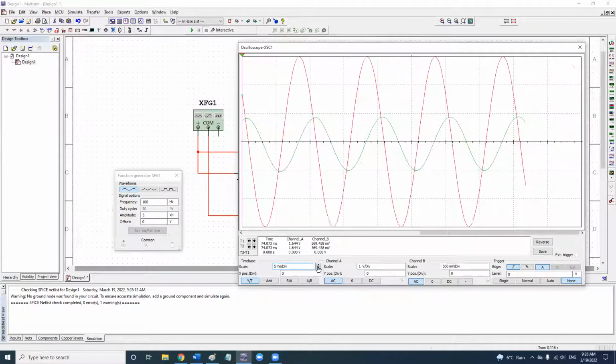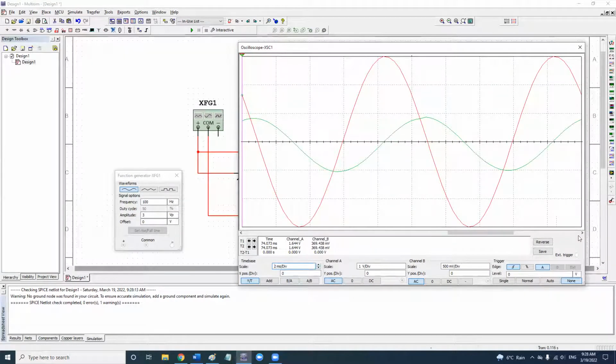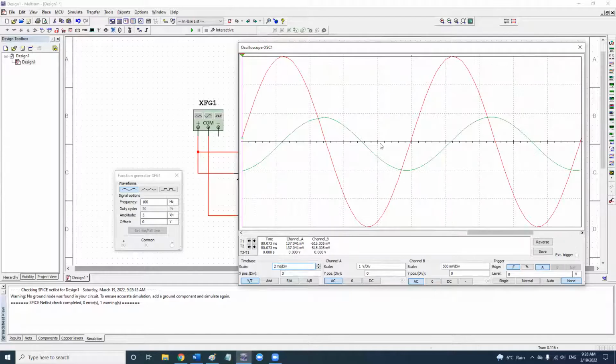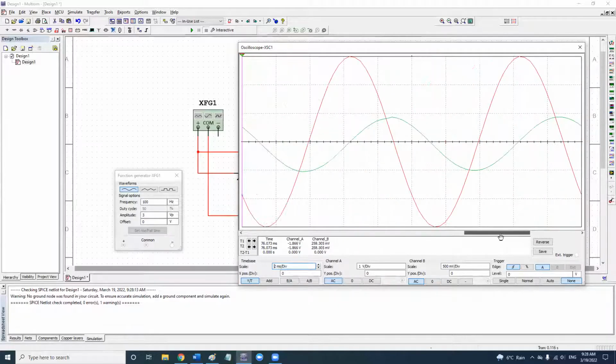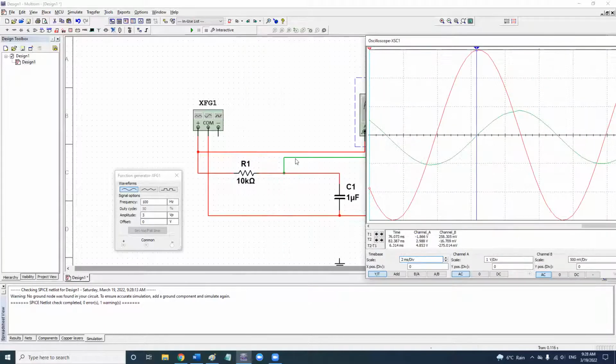Okay, so now I use different values. This should be more clear to see now. To measure the phase difference, first you find the 0 point. For example, the 0 for the green one. Can you guys see it? I'm at the 0 for the capacitor one, the output voltage. So make sure it goes to the 0 crossing, where the green wave crosses the 0.